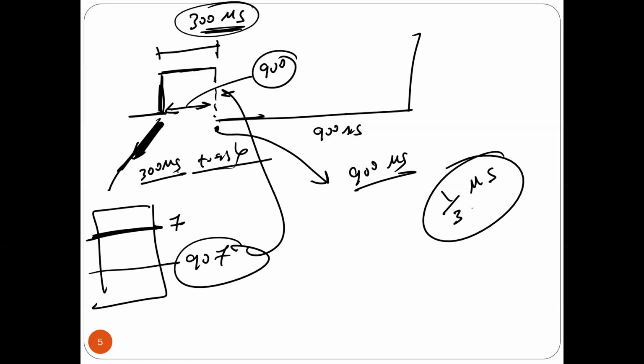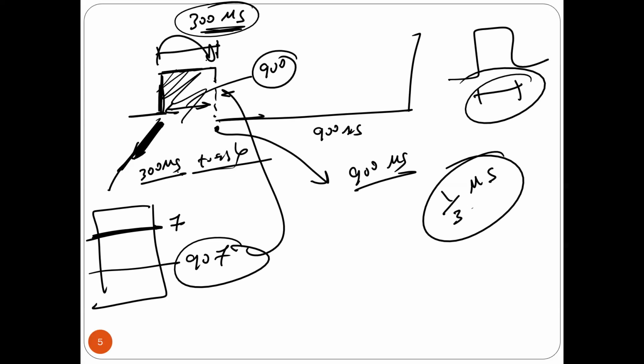So if you want to measure the time in input capture, this time is going to be a number of counts. Same thing if you want to generate a signal this way: I'm going to say I want to toggle after 500 counts, 600 counts. So here you get the time as a number of counts, and then you can convert the number of counts to time. When you want to generate a signal, I have to convert the time to number of counts, and I'm going to use that number in my program. I'm going to say, please, next time toggle after 900, or after 700, or after 1000, whatever. So you need to convert between counts and time. Anyway, I'm going to explain later in detail.